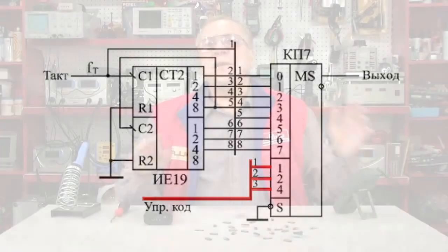Asynchronous counters are used not only for frequency dividers. In cases where high performance is not required, when transients at the outputs of the counter are also not that important, asynchronous counters might as well replace faster synchronous counters.